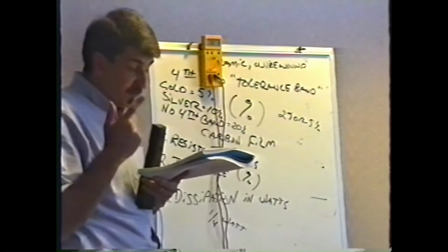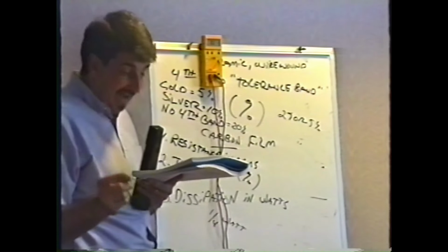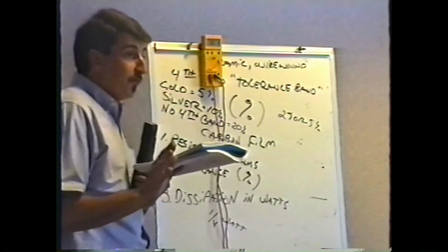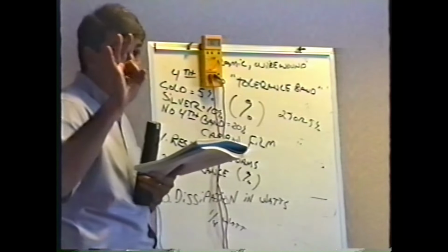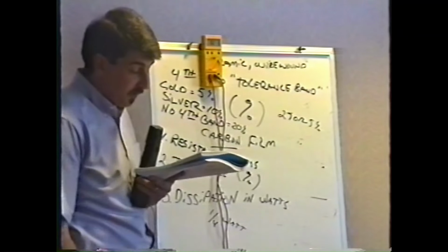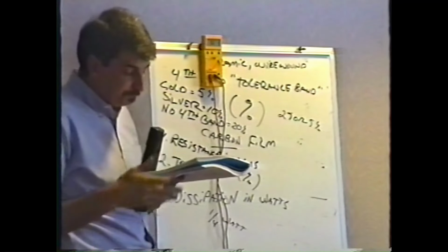Number 12 is also tricky like number 6. Brown, green, black is 15 ohms. If you put 150, you screwed up. Remember, the black band means no trailing zeros, no multiplier zeros, and 20%.